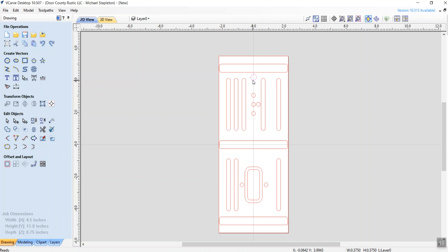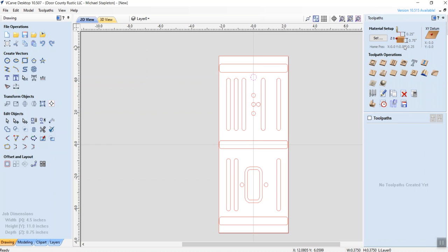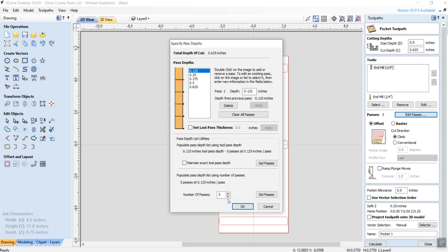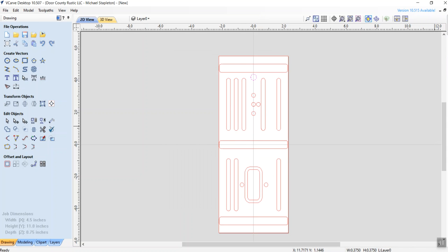So for instance, I'm going to start there. That's a 3/8 inch item, and so I am going to go to here. That one I want to be a 3/8. The pegs are only going to be 5/8 deep, so that's 0.625. And then this is PVC. Now I've got to be careful, because if I ever go into a different material, I don't want to have these settings, but I'm going to drop that down to 3 passes, which is fine in PVC.